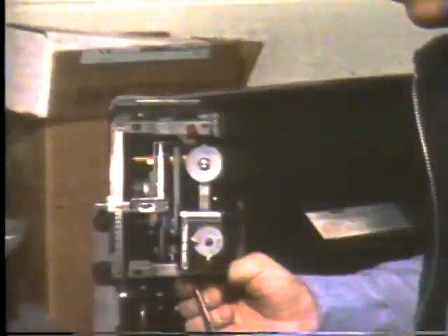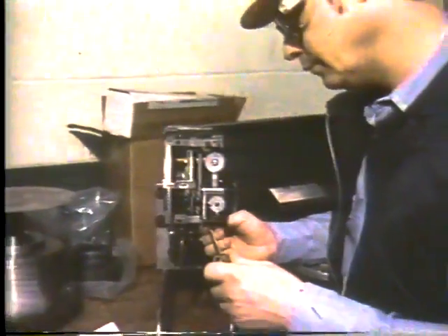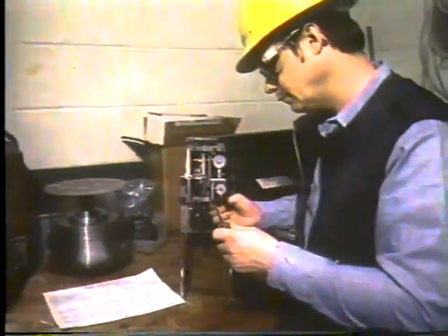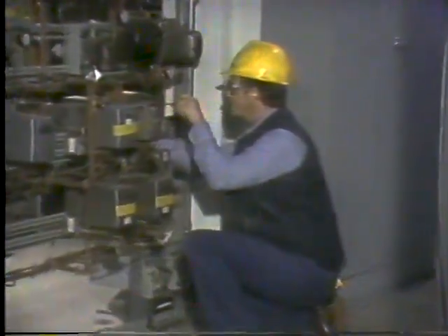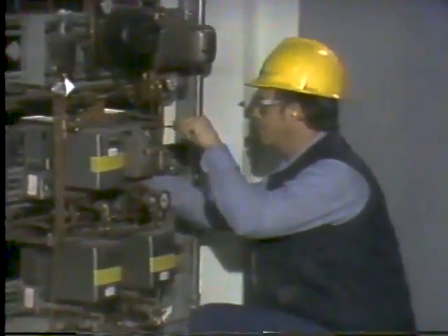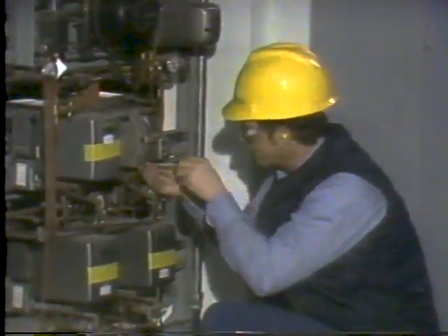So, after studying the system and deciding basically how he was going to tune it, the technician was ready to begin. He decided that he would remove the controller, take it to his shop, and calibrate it using the new settings. This is a standard procedure. After putting the controller back in the system, he planned to change set point 5% downward and see how the system responded. If the system stabilized at the new control point in about 15 minutes with minimum cycling, it would be tuned. If not, well, we'll see about that in the next part of the program.